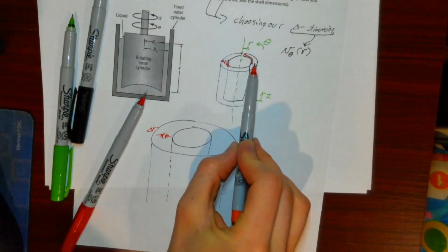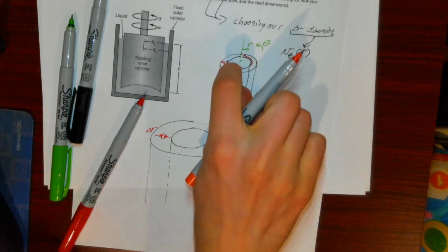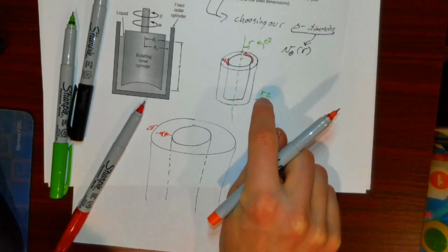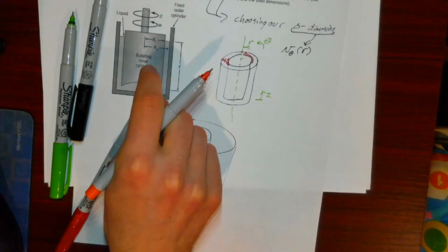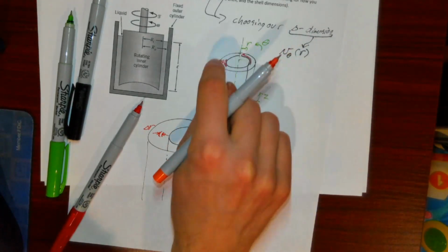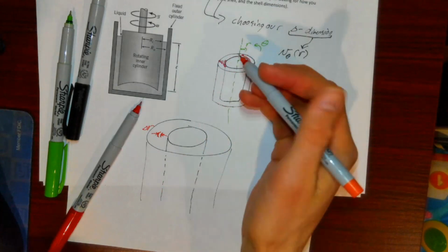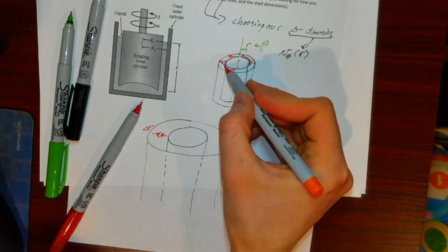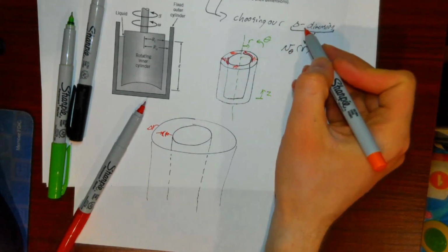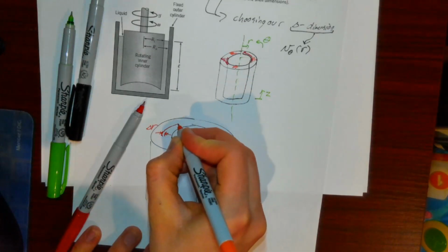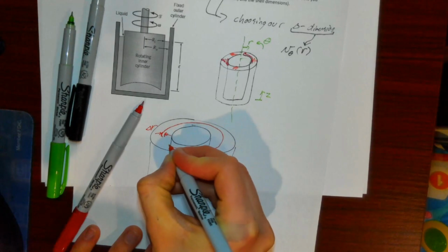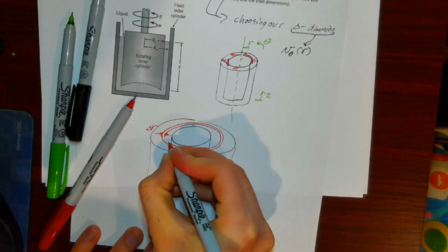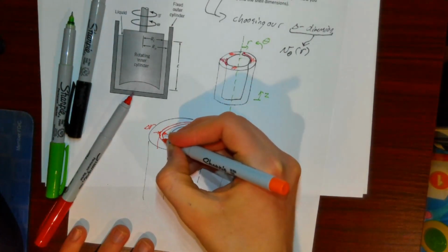We don't anticipate that this velocity is going to vary in any other direction. As long as there's nothing weird happening very close to the surface or the bottom, we wouldn't anticipate much variation with z. And as long as the cylinders are truly concentric and nothing weird is going on, there's nothing making this zone different from that zone, so there's no variation with theta. So we really only need r as our delta dimension, and that means our shell can be a hollow cylinder that is concentric and coaxial with all of the rest of the system here.